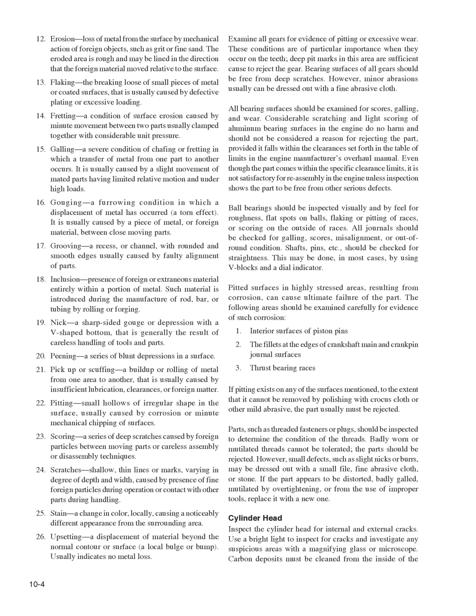24. Scratches, shallow, thin lines or marks, varying in degree of depth and width, caused by presence of fine foreign particles during operation or contact with other parts during handling. 25. Stain, a change in color, locally, causing a noticeably different appearance from the surrounding area. 26. Upsetting, a displacement of material beyond the normal contour or surface, a local bulge or bump. Usually indicates no metal loss.